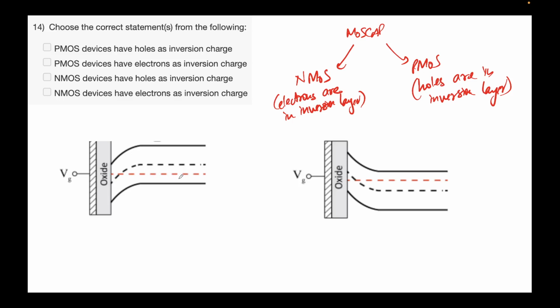I'll introduce that in a bit, but that's the nomenclature. Let's have a look at the image on your left. This is your metal, the dashed material shown, this is your oxide, and this is your semiconductor, and this is your EC, this is your EI, the intrinsic level, this is your EF, this is the EV. Forget about why the bands are bent, and let's not worry about that for now. Look here, EF is close to EV.